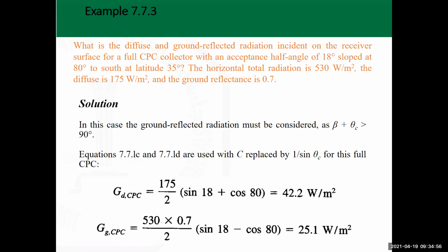Accordingly, you may do some sort of a parametric analysis. Suppose that it told you that you need 14 collectors, and the 14 collectors have given you a solar fraction of 60%. If I were you, I would say, well, what if I use 20? And then I record the solar fraction. What if I use 25? I record the solar fraction. I may keep on increasing it until I get a solar fraction of 100%, for example. And then I would know how many I need to cover all the load that I need for water heating.